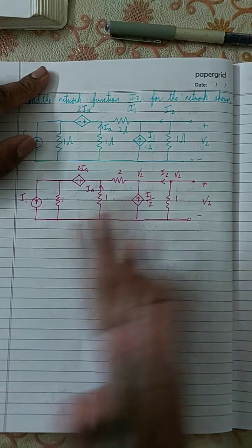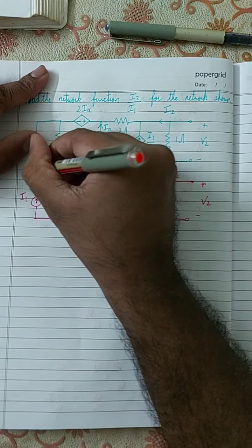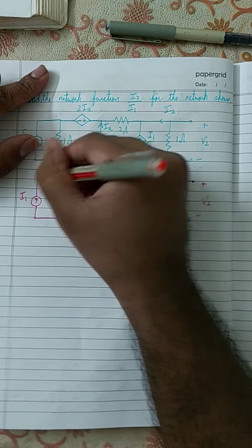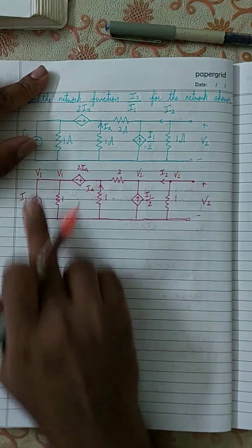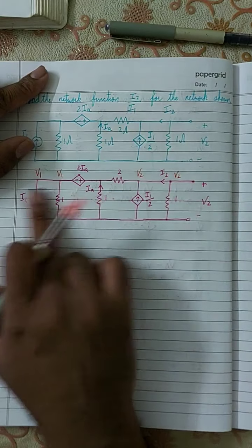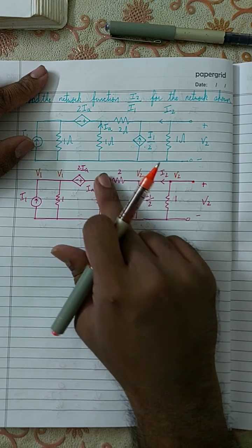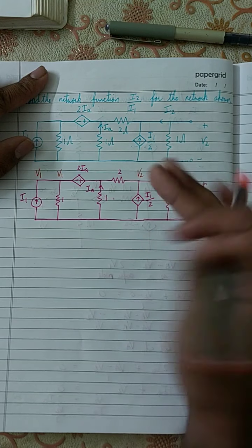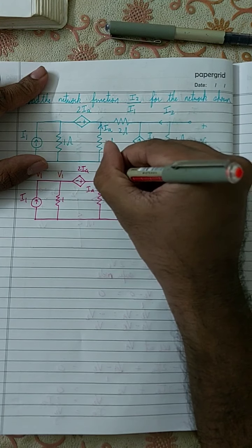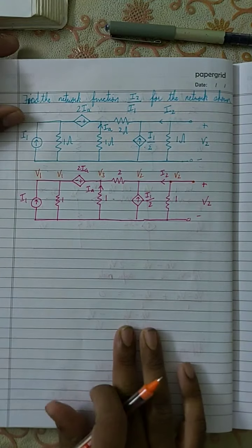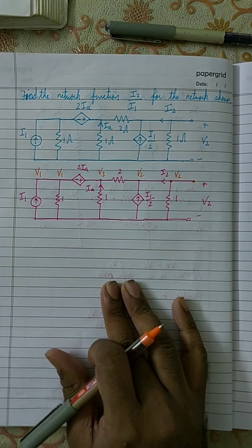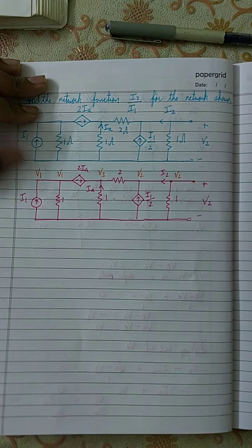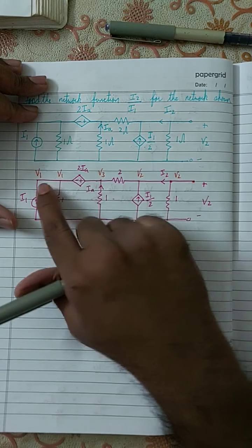And likewise, if you look over here, there's no V1 written, so I will mark this as V1. Okay, this is V1. So if this is V1, then this is also V1. So this entire branch is also V1. And if this is V2 and this is V1, then this is another branch, right? So what name should I give this branch? I can either name it VA or V3. I'll call this V3. Okay, there, you can give any name you want. So therefore this circuit has only 3 nodes, that is V2, V3 and V1.